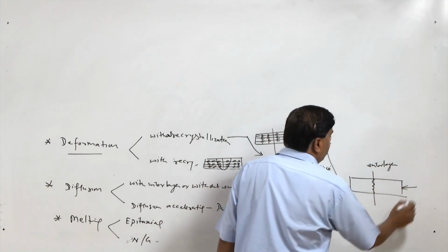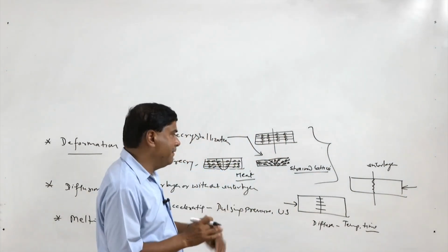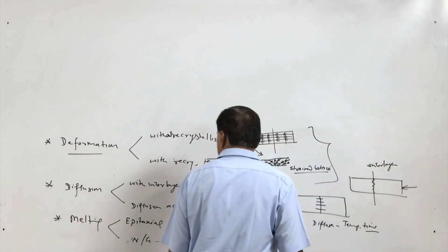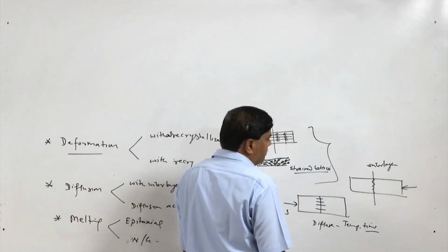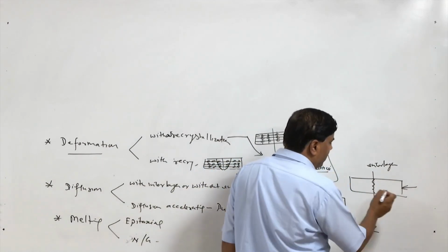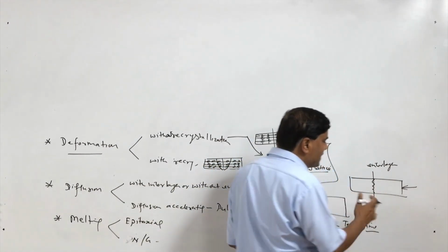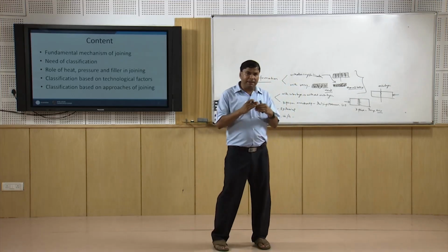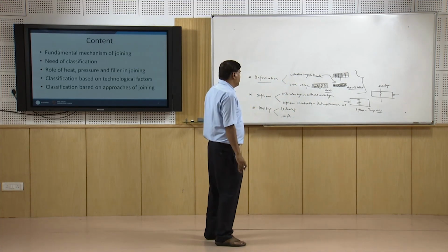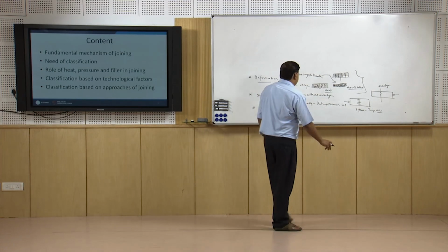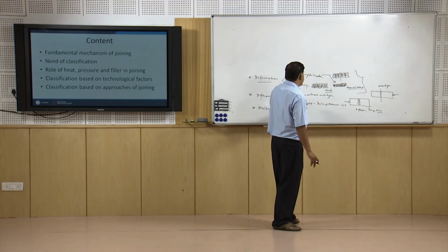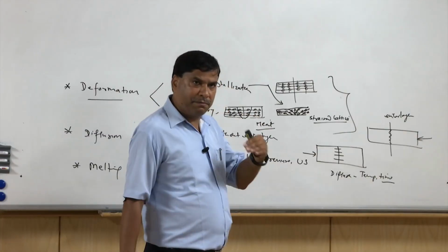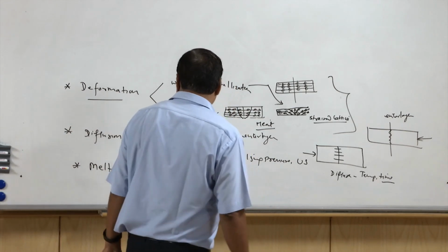Under pressure they get deformed and fill the cavities and irregularities present at the surface in order to facilitate the diffusion across the interface. Sometimes pulsating pressures are also used, so that the peaks and valleys collapse under the pulsing pressure conditions and bring the metallic surfaces into firm contact with each other. Similarly, the use of ultrasonic vibrations also helps in facilitating the diffusion across the interface, so that the diffusion bond can be developed at a much faster rate.